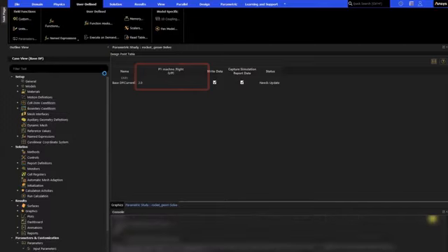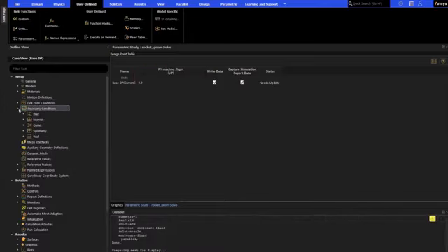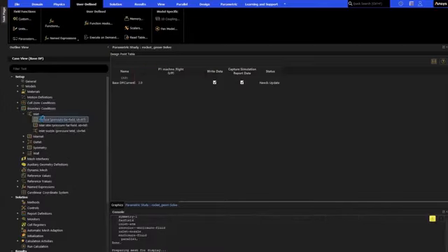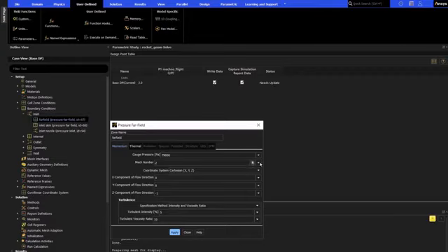The input expression is then selected in the Boundary Conditions pane, and additional expressions can be created for other variable boundary inputs, including the atmospheric pressure and temperature, by selecting New Input Parameter in the dropdown.